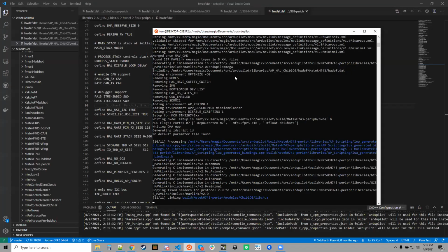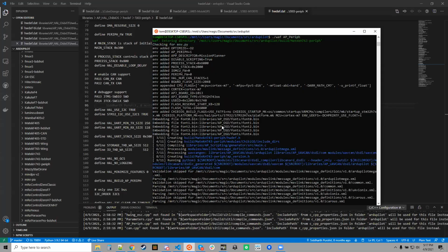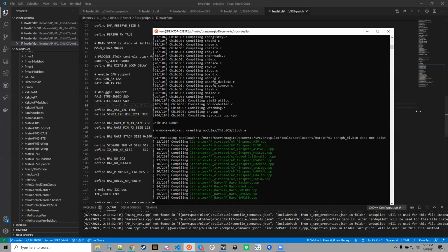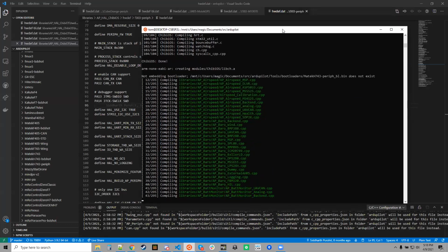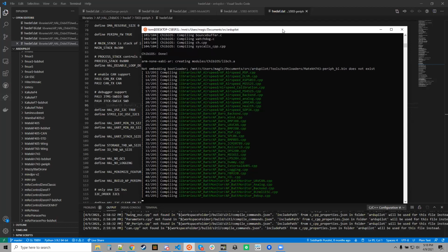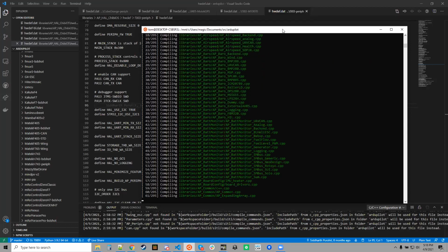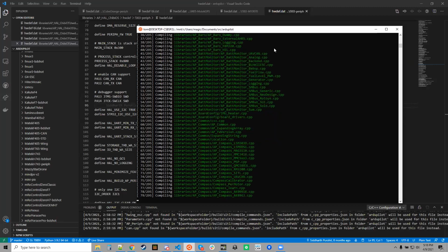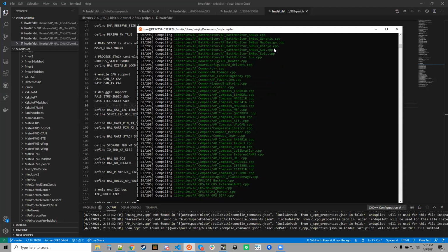So this is interesting. The AP OSD was loading on that. Yeah, that's just because of the include of the hwdef.dat from the Cube Orange, and that has the wildcard pattern for the OSD fonts. So it's embedding the fonts, but it won't actually link the OSD library, so you can't do anything with it.